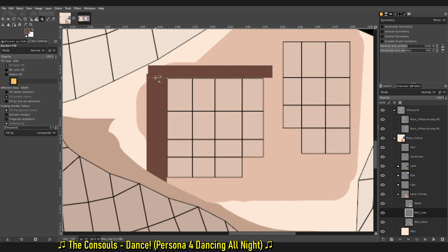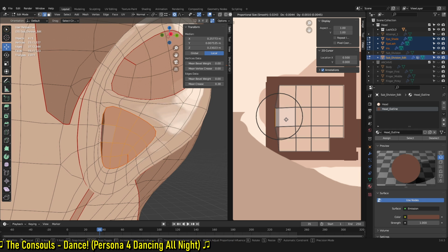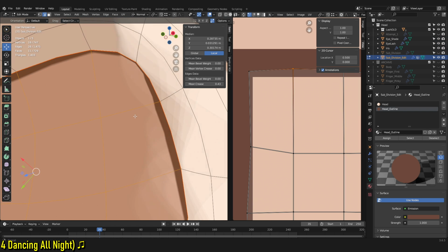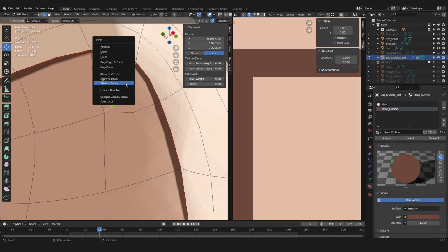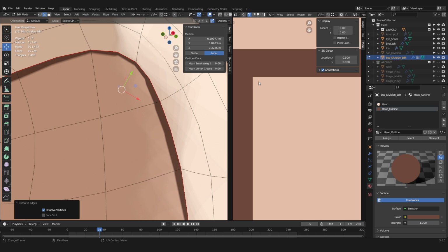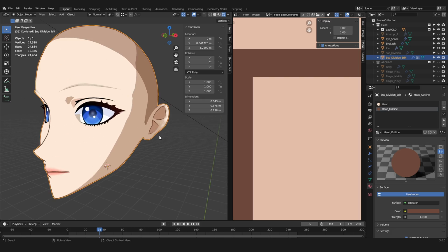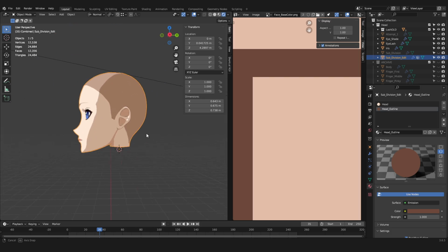Now if you border UV with another colour, you can drag out the verts to make the outline appear how you want. At times you'll find the line isn't how you expect it. This is down to how the triangles are aligned within the quad. You can adjust this by cutting the quad with the knife tool from corner to corner, then press X and dissolve edges to return it to a quad. There are a lot of other ways you can utilise this technique that I may cover in future videos, but for now, I think that covers it for UV mapping.